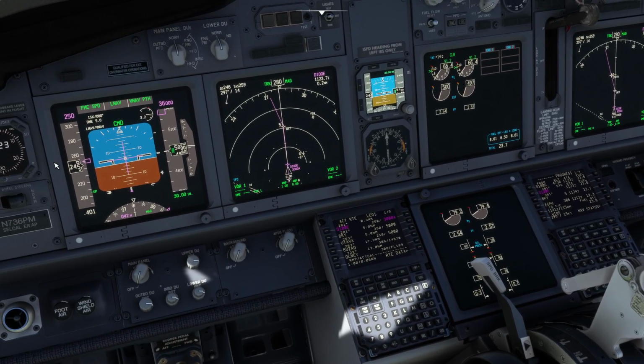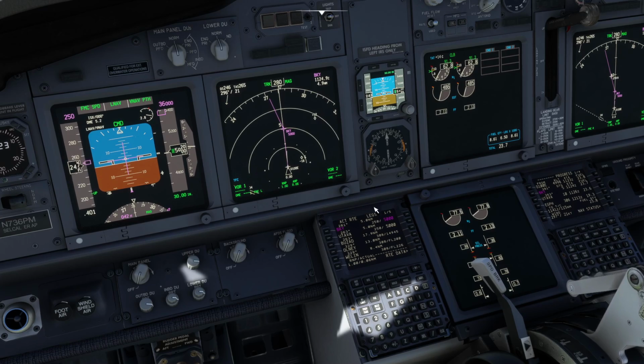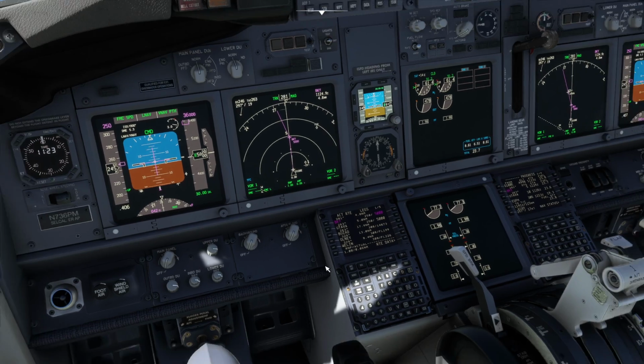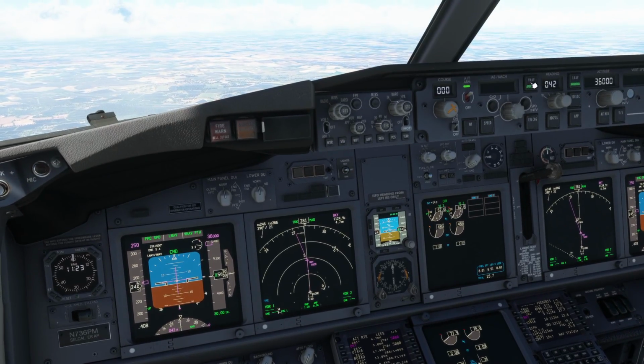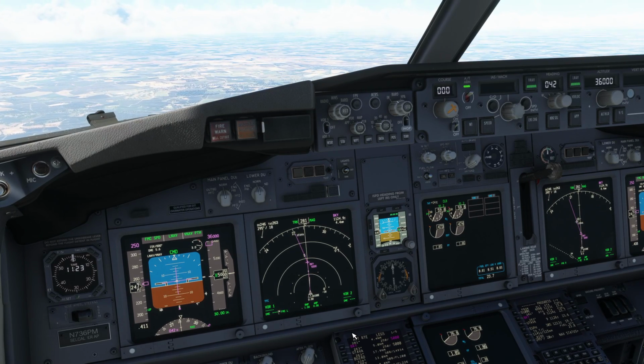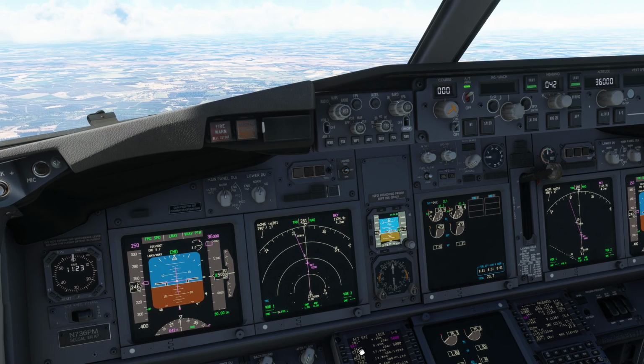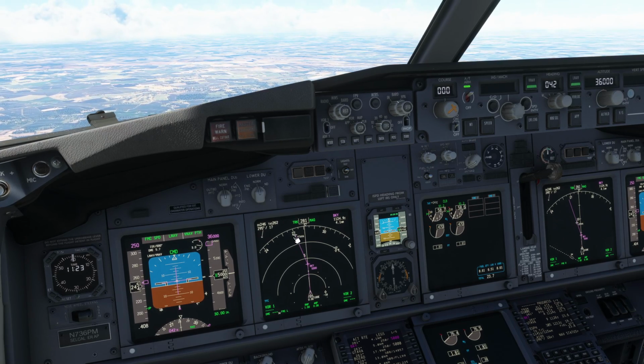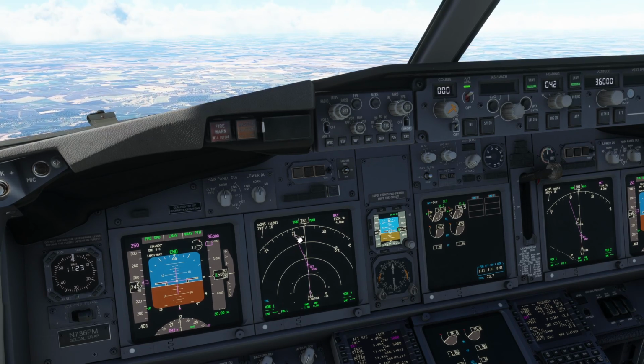So it's gone to 5,000 early, and it's just hovering around below 250 knots. So basically, the VNAV is following the restrictions. So as and when it can climb, it will. Once we go through Utava, which is just coming up here, it will start climbing again.